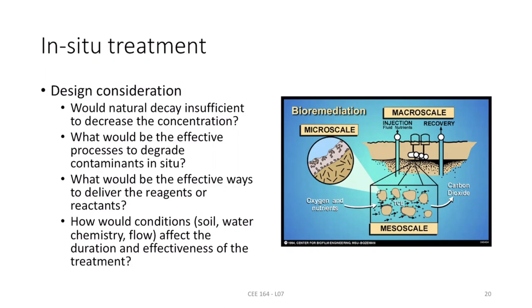The same way, if we inject these oxidants into the ground, you are killing lots of microorganisms which are helpful for other functions. That's why in-situ oxidation is the last method, used where there are so many pollutants that you really don't care. You just want to remove them as quickly as possible so that once the pollutants are gone, the native microorganisms will grow back. On the other hand, bioremediation is more efficient in that context.